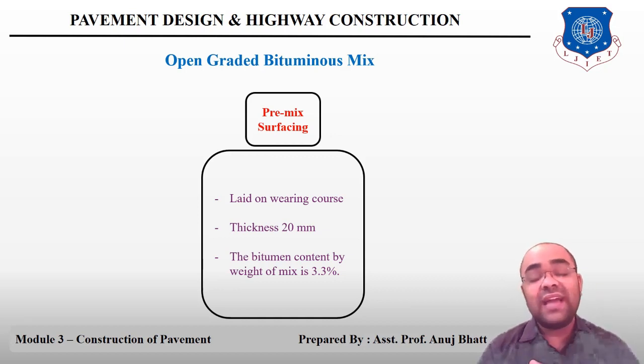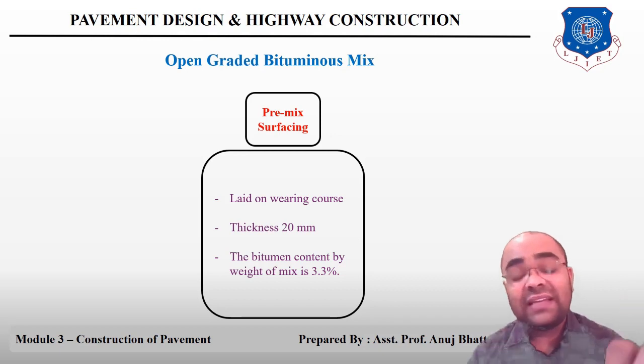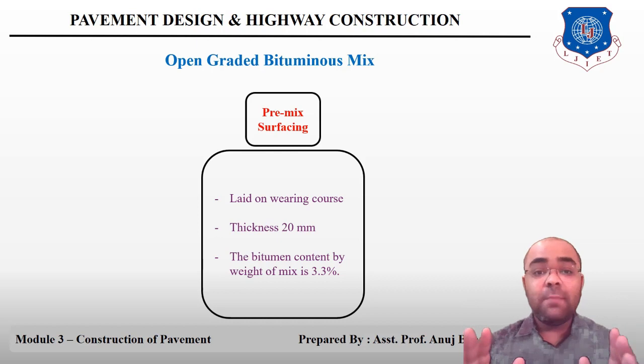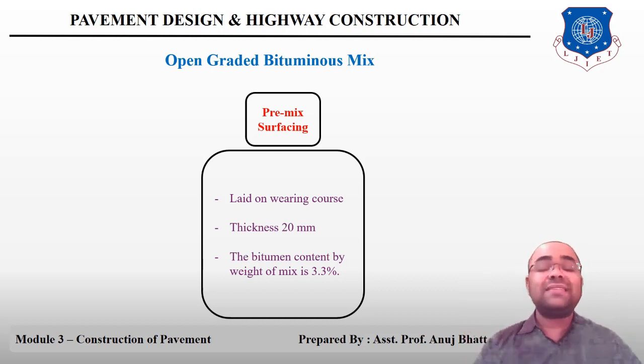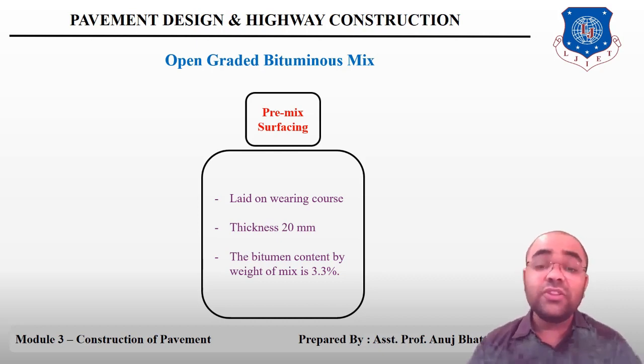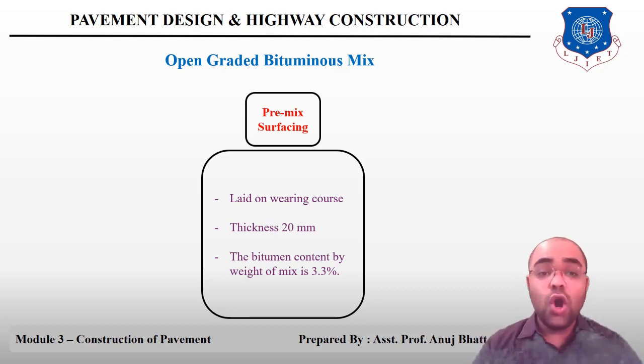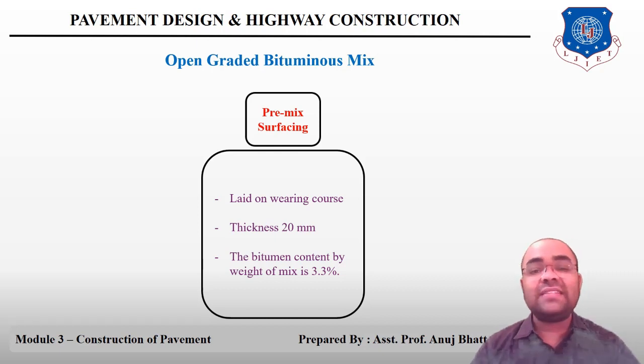First you have to heat the aggregate so that any moisture in it can be removed. The difference in temperature between the binder and the aggregate shall not exceed 14 degrees Celsius. The mixing shall be thorough to ensure that a homogeneous mix is obtained, in which all the particles of the aggregates are coated uniformly.